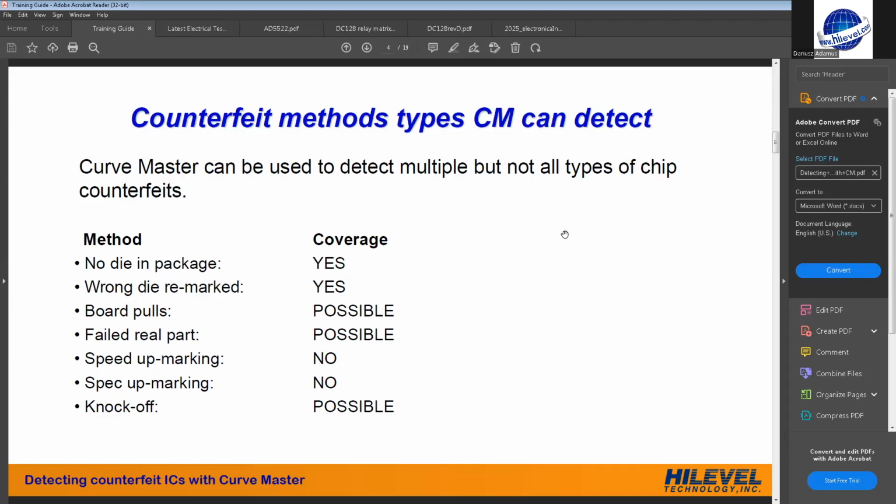And again, some pins will fail, so you can detect it. And also sometimes the chips have older generations, like a revision for the die. There are differences between different revisions of the dies with slightly different characteristics. And then you can actually detect that, okay, this is an older revision and the marking says this is the latest revision, and you know that's something wrong.